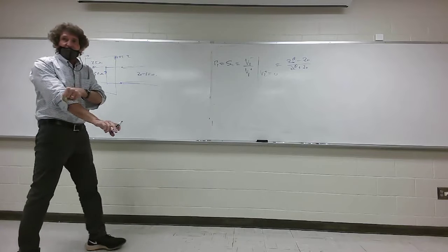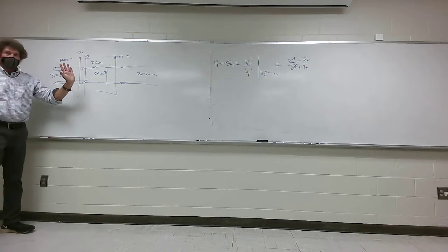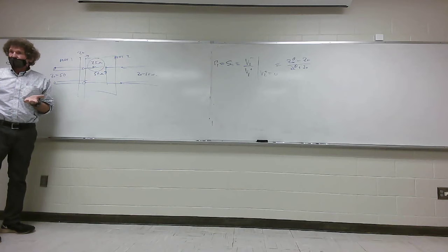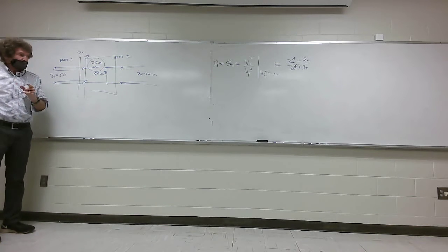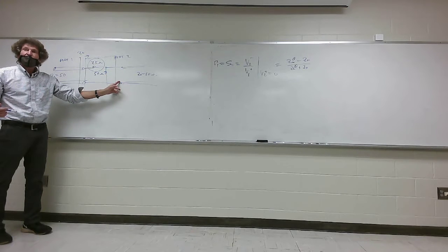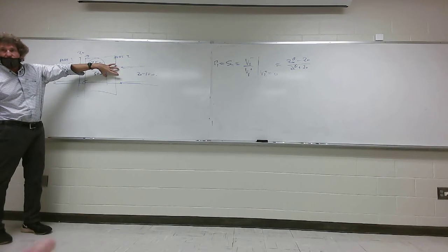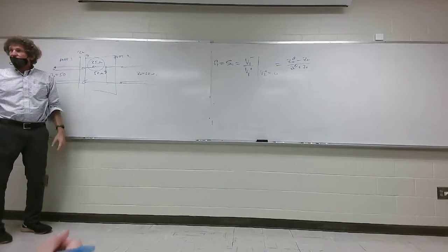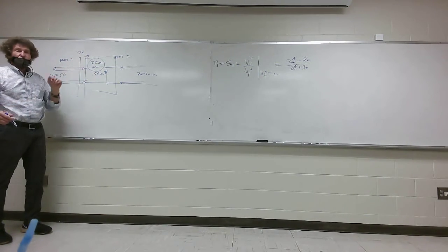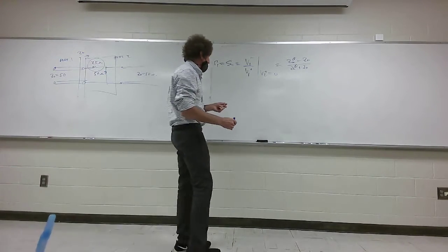How do we get Zin here? Now, pay attention to this. Here's where people foul this up. All right, I'm looking right here. I want the input impedance. You see how the 25 ohms is in series with whatever, right? Now look, there's 50 that goes to ground, but there's 50 ohms on that line. They are in parallel. Y'all hear me? So this would have an equivalent of 25. Y'all see that? Y'all see it in the back there, guys? All right, that means the input impedance, 25 and 25, or 50, right? What do you notice happening?